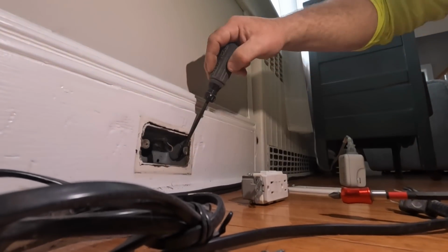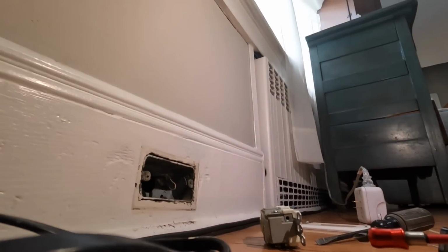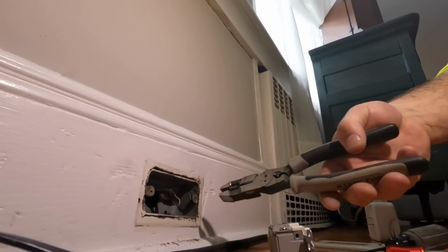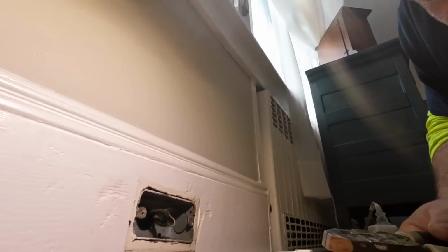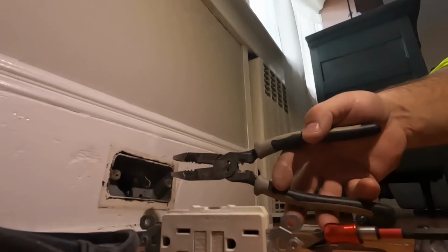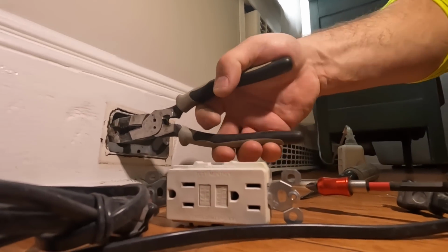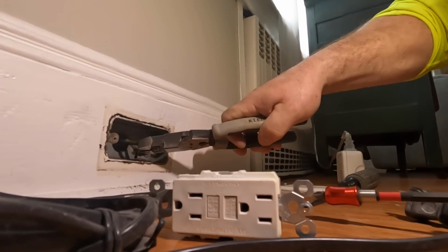So sometimes you never know what you're going to find, and I wasn't expecting a handy box to be here, which is not a big deal. But as I found out, the connector is not connected to the box, so therefore the armored sheathing around the conductors that makes up the equipment grounding conductor is not bonded to this metal box, so therefore the metal box is not grounded properly. So we're going to remove this box, remove the cable, run some Romex up here, and do it right. See, the trouble is that the connector's not in the box.